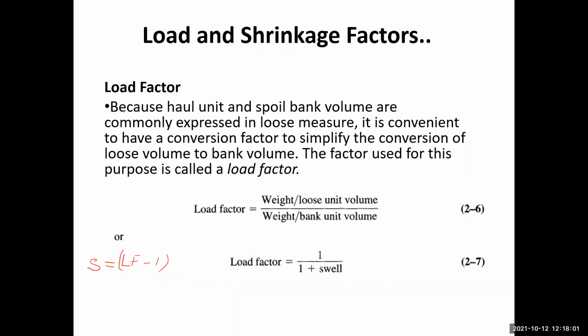So anyway, the load factor is basically the ratio of the weight per loose volume and the weight per bank unit volume, or it can also be related to the swell. So load factor is equal to 1 over 1 plus the swell. So very easily we can derive it.